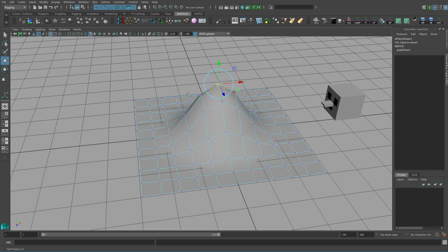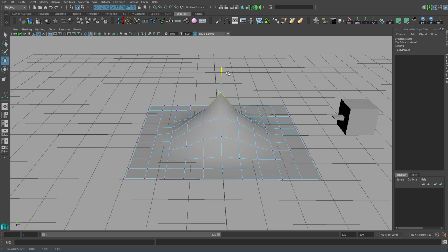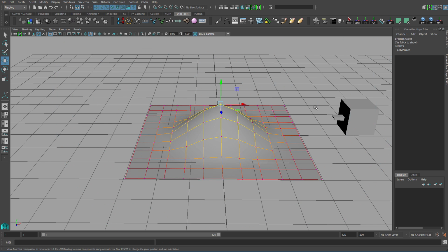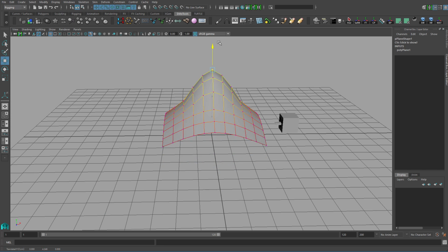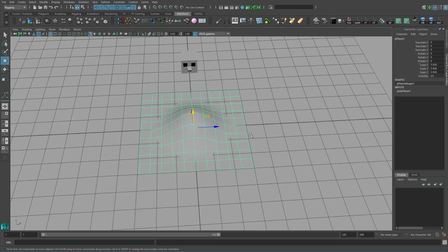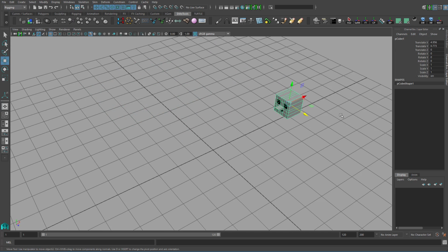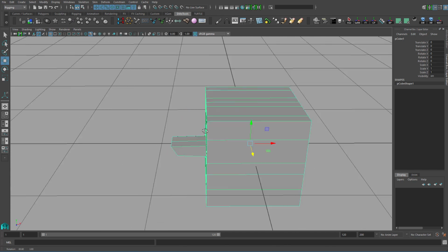Now how much you're affecting the surrounding area will be based on the radius of this circle. If you make a very small radius, it's not going to change anything. If you make it really big, it can change a lot of things. So in other words, holding down B and left mouse button drag, that's how you change the falloff of your soft selection. Okay, that's soft selection. That concludes the basic moving tools.